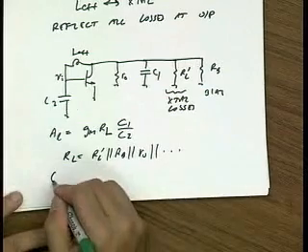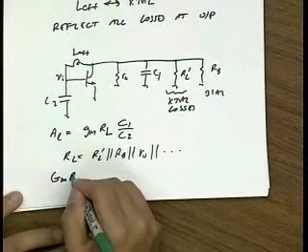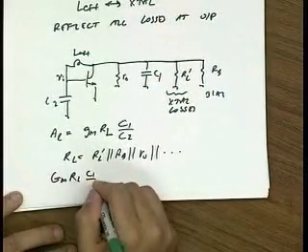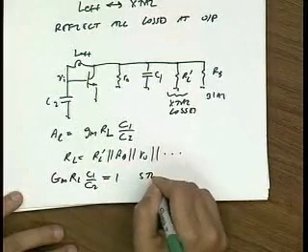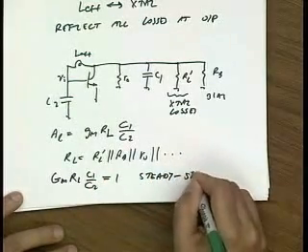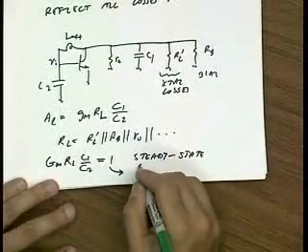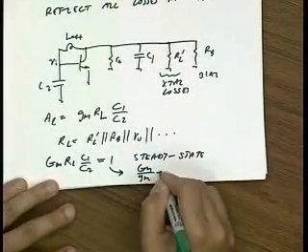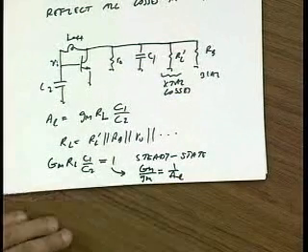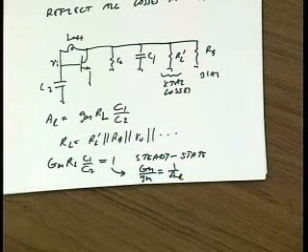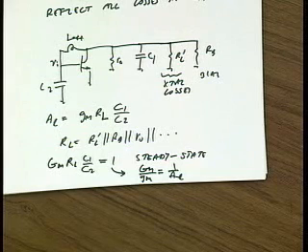Same equations as before. For large signals, we use the large signal g_m. We know in steady state the loop gain is 1, and that allows us to calculate the amplitude of oscillation based on the initial loop gain.